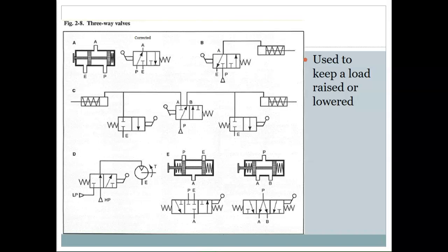Okay? Everybody following so far? So what you have right here, when you have 2 springs on either side of a valve drawing, first of all, you have the middle position. That is going to be the neutral position, because whether you actuate it left or right, once you relieve pressure off your manual actuator, these springs are just going to spring it back to the center position.